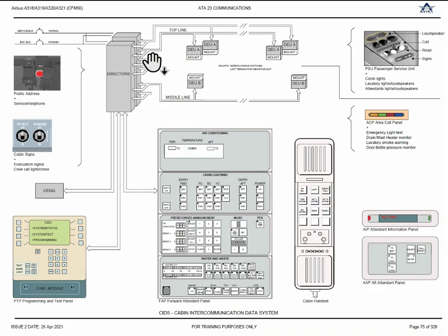The system is designed around two directors, which you call director one and director two, and they manage every function of the cabin. Now, to interact with the passengers, you have a DEU A, decoder encoder unit A. They are connected with some top line buses. We'll discuss in detail.